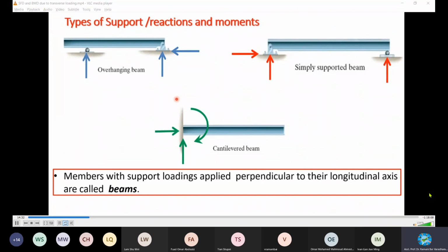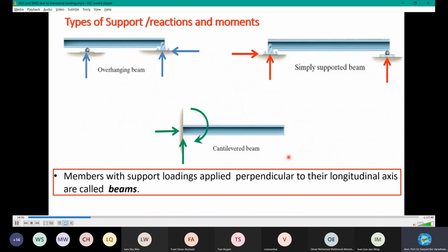And this is the cantilever beam. A cantilever beam is one that is completely fixed, maybe driven into the wall or welded, riveted with brackets and so on, firmly into the wall, into the structure, into the frame. It is totally restrained. Moment is totally arrested for this member. And the other end is free. Then it is called a cantilever. This cannot be called a cantilever because this end is just pinned. You may think, here also we have a free end, so why not a cantilever? No, it cannot be. It's overhanging because of the pin. If it is fixed here, then it can be treated as a cantilever. I repeat, one end fixed and the other end free means cantilever.